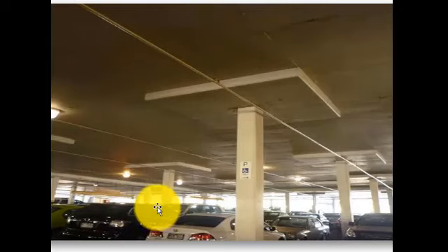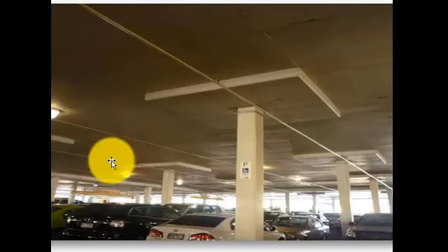So when should you consider using a flat slab in your design? You should consider a flat slab in a case whereby you don't need partition, or you need a little partition. For example, when you are designing a car park, look at this picture I'm showing you. It is a car park as well. When you're designing a car park, there will be no rooms or toilet in the car park. So there are no partitions. Then you should consider a flat slab.